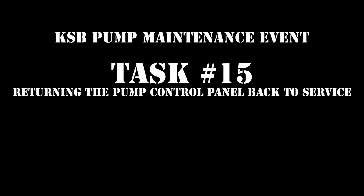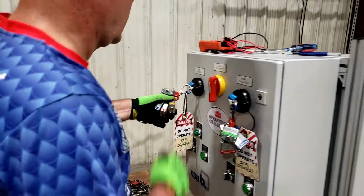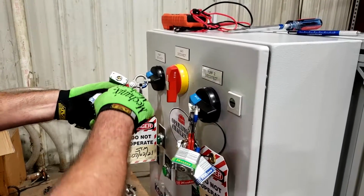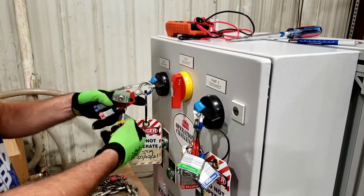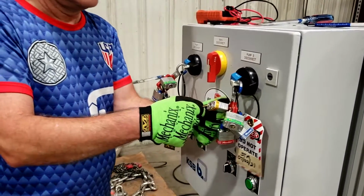KSB Pump Maintenance Event Task 15. Returning the pump control panel back to service. Remove the locks, gang hasp, and tags from pump 1 and pump 2 disconnect. Each individual that is locked out is responsible for removing their own lock. You may not remove the lock for another team member.